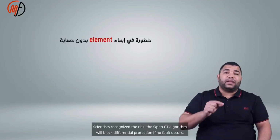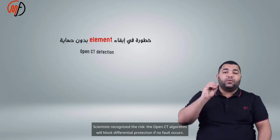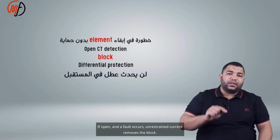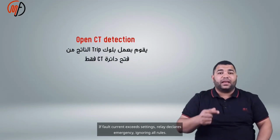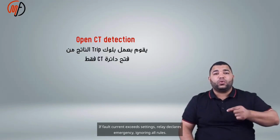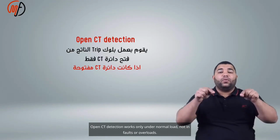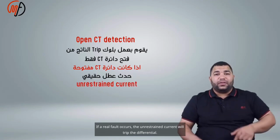Scientists recognize the risk. The open CT algorithm will block differential protection if no fault occurs. If it is open and a fault occurs, the unrestrained current removes the block. If the fault current exceeds the settings, the relay declares an emergency, ignoring all rules. Open CT detection works only under normal load, not in faults or overloads. If a real fault occurs, the unrestrained current will trip the differential.